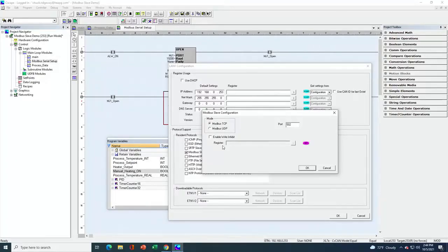And in the Ethernet supplement is a chapter on Modbus TCP server and Modbus serial slave. And you'll see, it's mainly going to cover Modbus TCP server because it's an Ethernet supplement. But in there is going to be the Modbus map, complete Modbus map between Modbus registers and Horner registers. If you've got that in front of you, that's really the key reference information you need.